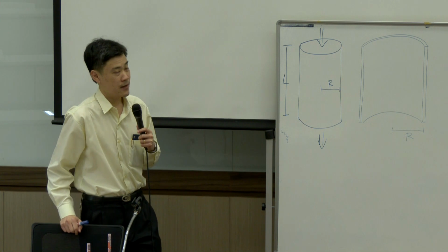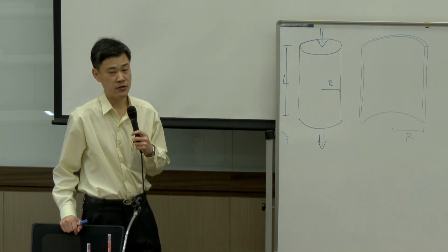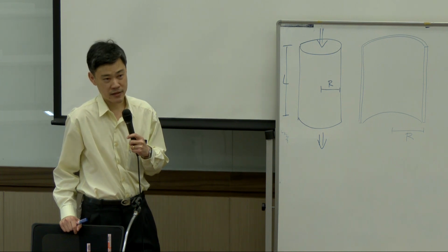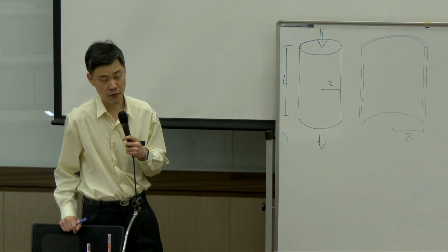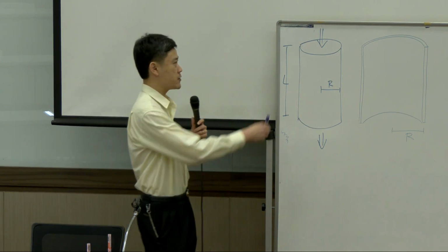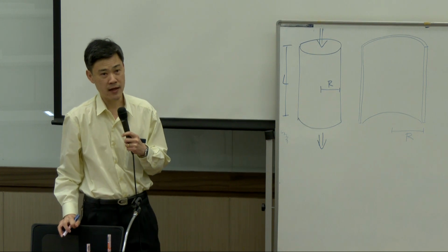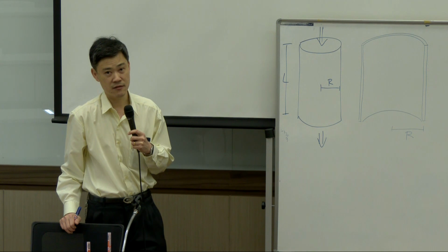Then we have to assign the origin point. As I said, one axis is supposed to go in the direction of the flow. That would be easier. So if flow is going down, the axis in cylindrical coordinate that will go down is supposed to be the z-axis.